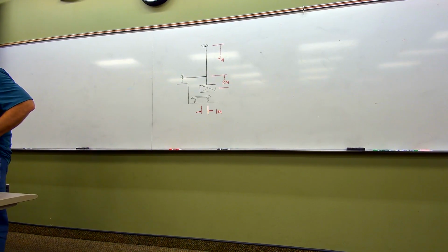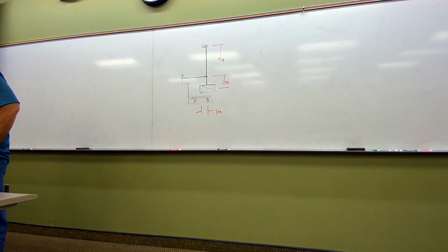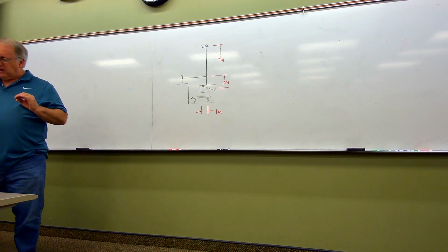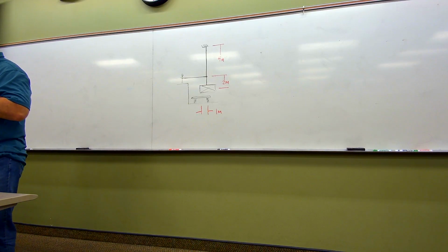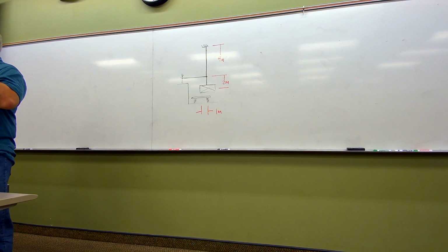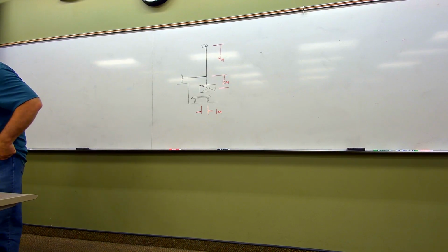I heard a couple of important words. Horizontal force. Why do you think they included the word horizontal? Like, who cares otherwise? What do you think? That way you know it's directly aligned, parallel to the x-axis. Exactly right. If we use a standard x and y coordinate axis system, that's signaling you that there's no angle on this. It's going to be a purely x-directional force. So we got that part. We know the worker is exerting this on the what? The rope. So therefore, that can only be a tension member. We got that part down.